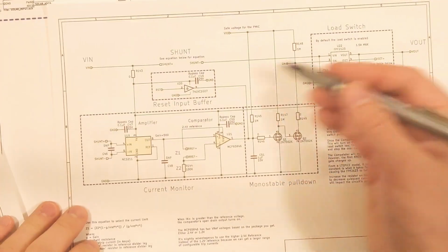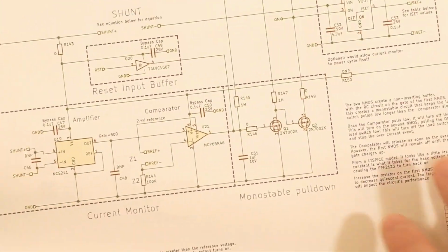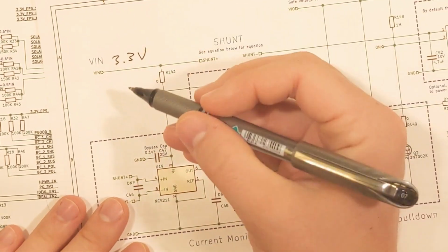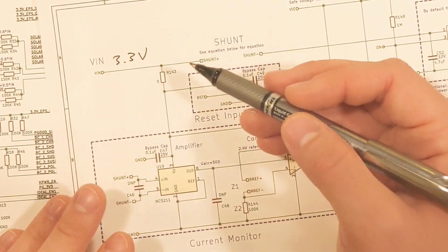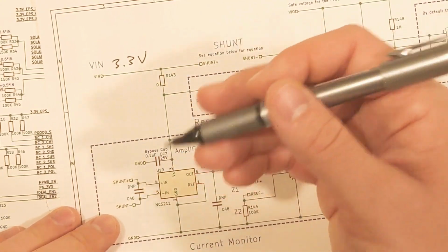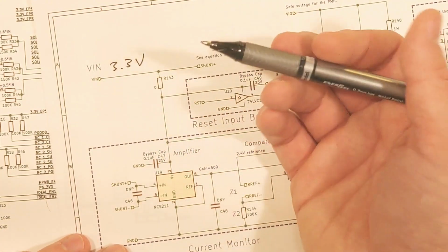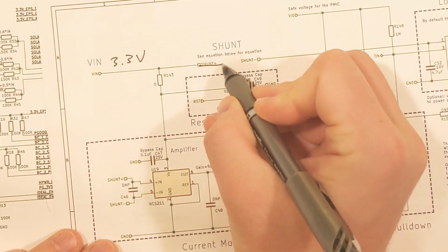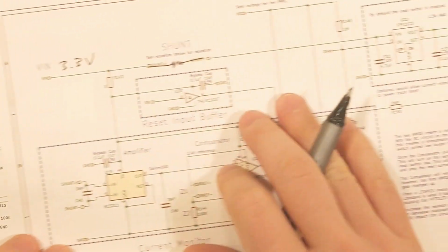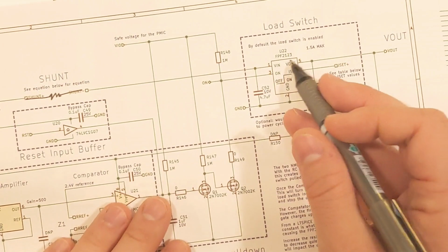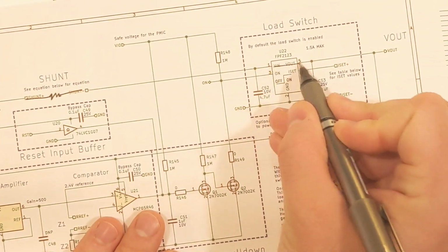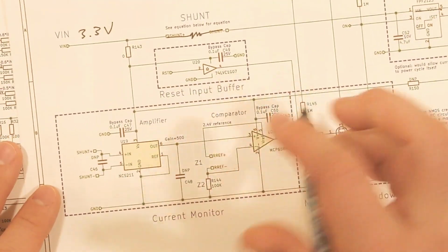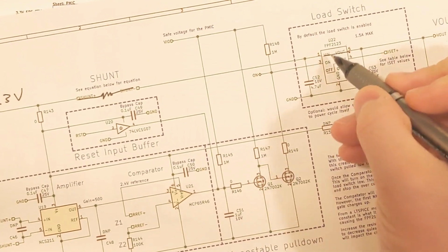I also spent way too much time making all of these schematics pretty. So voltage comes in here, and that's 3.3 volts for this circuit. It could be 3 volts, it could be 3.5 volts, it could be 2.8 volts or 2 volts or whatever, but I'm only using 3.3 volts for now. So this voltage comes in, it goes through a shunt resistor, and then goes into the FPF1213, where it's switched on, and it'll go to the output. That's the path, and there's a whole bunch of other stuff which will control this FPF1213.